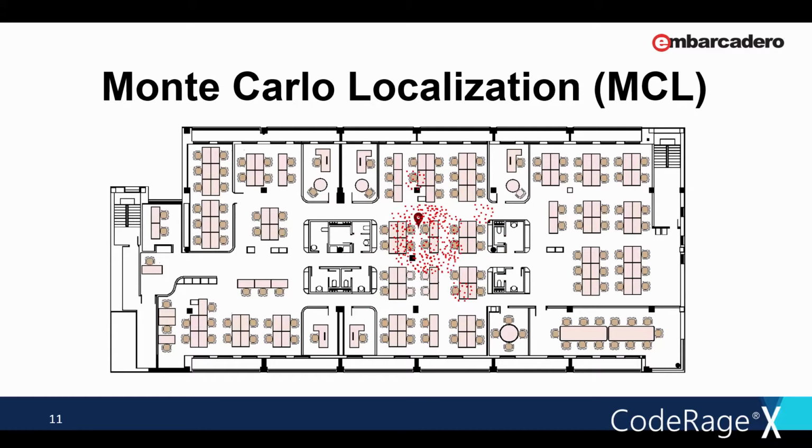Whenever the robot senses something, the particles are resampled based on recursive Bayesian estimation. This is how well the actual sensed data correlate with the predicted state. Ultimately, the particles should converge towards the actual position of the robot. So it is obvious that for our purpose, the robot will be a Bluetooth LE mobile user and the sensed data, the estimated distance to each beacon.